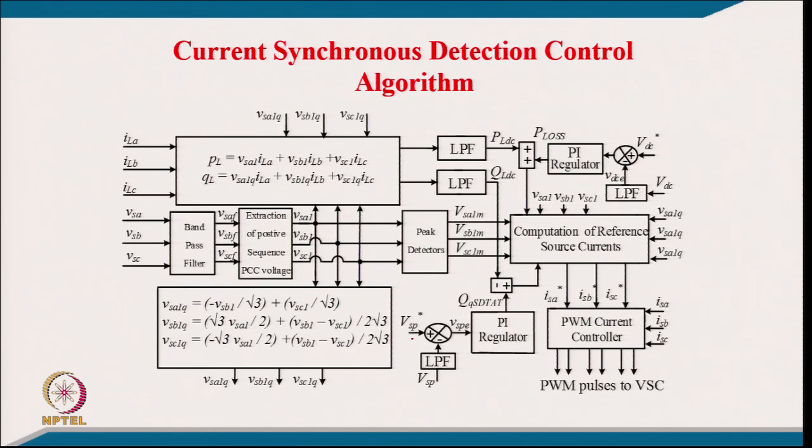Similarly, for reactive power we get it from voltage regulation: we have a reference voltage, we have the estimated peak of voltage, and from this we get the error, and we use the PI control. So, this is the current D-STATCOM minus the load, that is the reactive power that has to flow in the supply. So, we have active power, we have reactive power to be taken from the supply system, and we have a positive sequence voltage in phase and quadrature, and we get typically the supply current here for this current synchronous detection method, and we have a sensed supply current, we give the gating signal. Again here also, if we make this 0, it will be modified for unity power factor operation, and if it is there then it will be for zero voltage regulation.